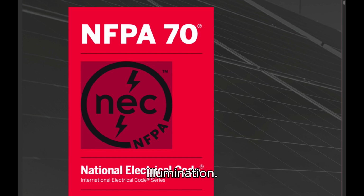D. Illumination. Illumination shall be provided for all working spaces about service equipment, switchboards, switchgear, panelboards, or motor control centers installed indoors. Control by automatic means only shall not be permitted. Additional lighting outlets shall not be required where the workspace is illuminated by an adjacent light source or as permitted by 210.70(A)(1), Exception No. 1, for switched receptacles.